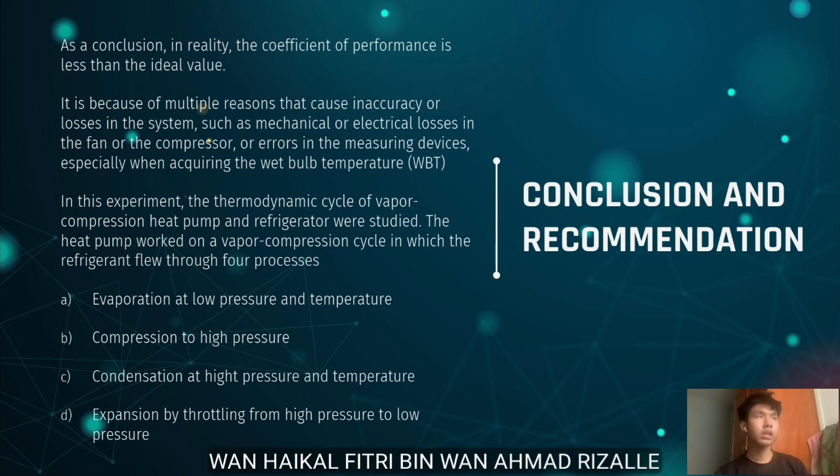In this experiment, the thermodynamic cycle of the vapor compression heat pump and refrigerator was studied. The heat pump worked on a vapor compression cycle in which the refrigerant flowed through 4 processes. First, evaporation at low pressure and temperature. Second, compression to high pressure. Third, condensation at high pressure and temperature. And the last one is expansion by throttling from high pressure to low pressure.